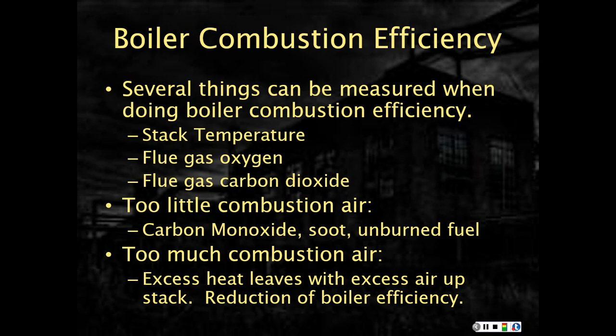Now, too much combustion air. Like we mentioned before, with too much combustion air, excessive heat leaves with the excess air up the stack, and again we have a reduction in boiler efficiency. Now if we go back to too little combustion air, it's obvious why making carbon monoxide is a bad idea. Now the soot: if we start depositing soot on heat exchanger surfaces, we also reduce the heat transfer rate of the heat exchanger. So either condition is not good and adversely impacts the efficiency of a boiler.